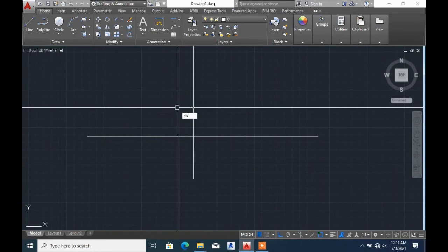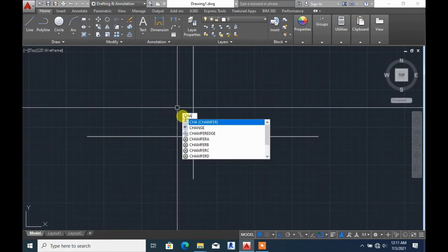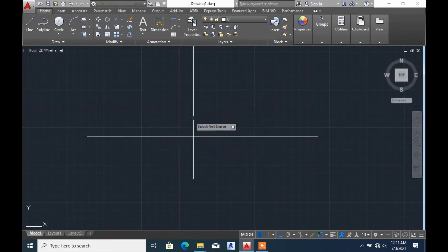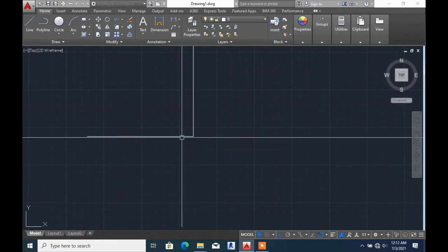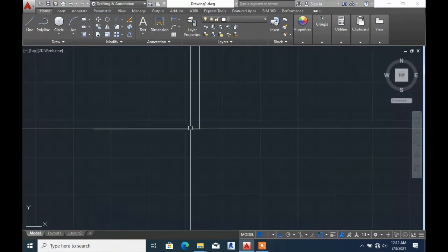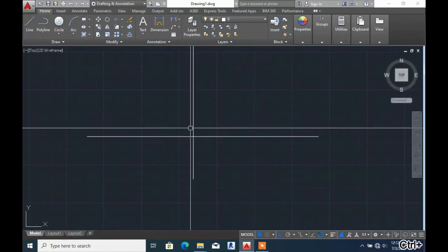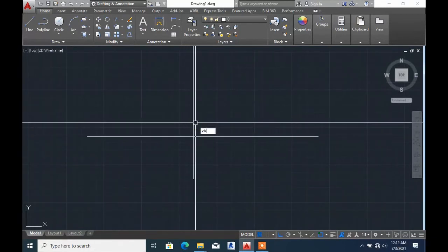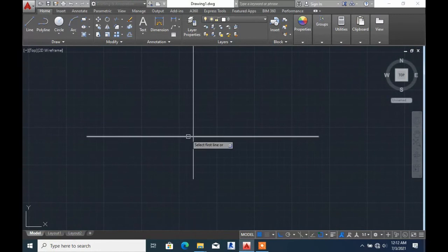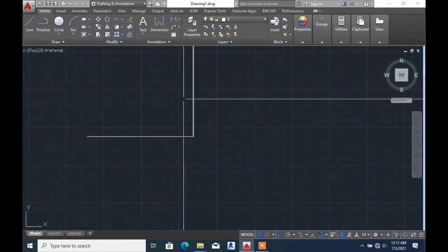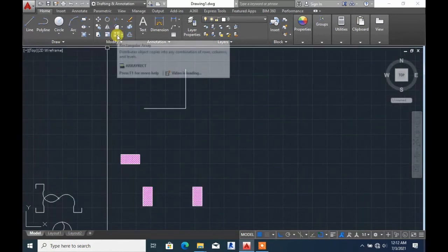Type CHA, enter, then click on this one to chamfer. CHA, enter, click here, the line will chamfer.